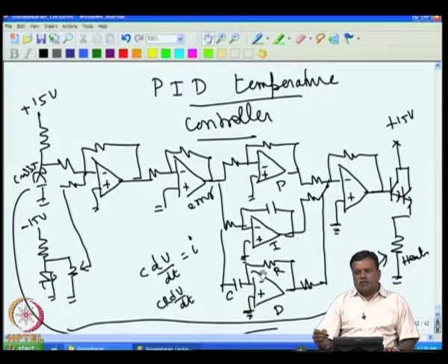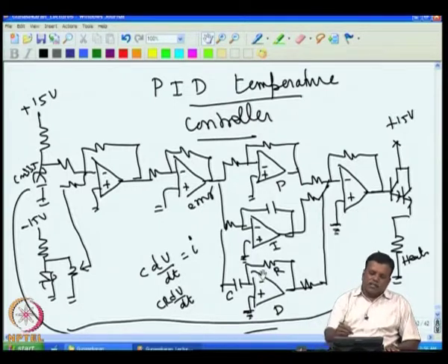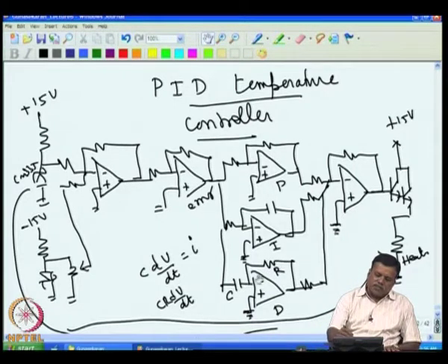Normally we try to make a sensor which is fast responding, because only then do we get a large ratio between the system time constant and the temperature sensor time constant. Normally the system time constant is larger and the sensor time constant is smaller. So we try to match the smallest time constant to the differentiator.